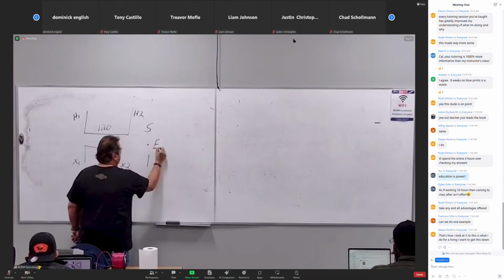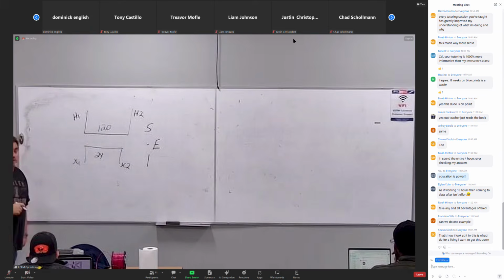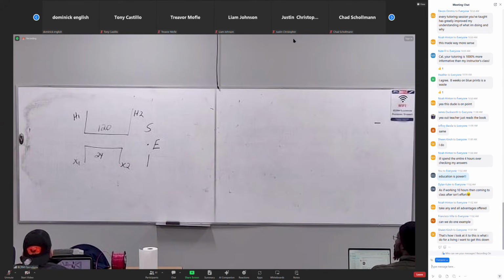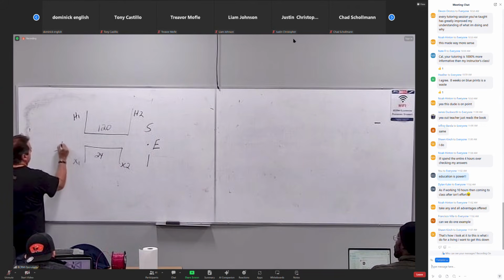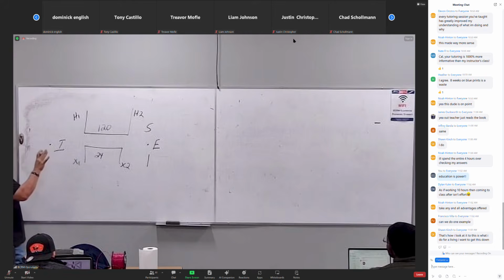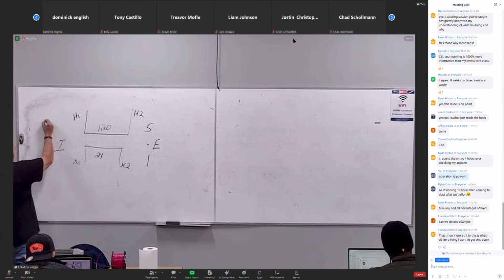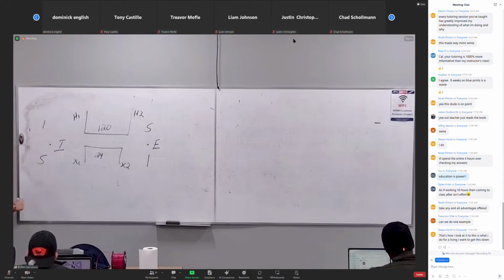This is the voltage ratio. Here's what we know about transformers. If power in equals power out, that means if the power stays the same, if the load stays the same, if I adjust voltage, then I must inversely adjust current. So what is my current ratio? I don't need to do any math. It's what? 1 to 5, right? You're like, how does that work, Cal? How can that be? If I'm 5-to-1 and I'm 1 to 5, well, it's simple.